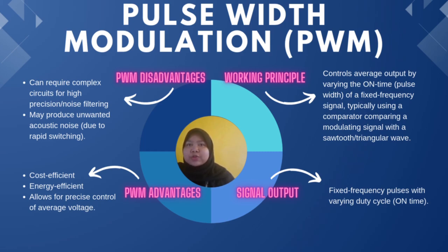However, PWM also has its disadvantages. It can sometimes require complex circuits for high precision or noise filtering. Additionally, the rapid switching involved in PWM can produce unwanted acoustic noise, which might be a concern in certain environments with specific types of loads, such as motors.